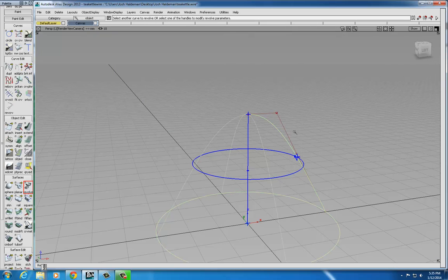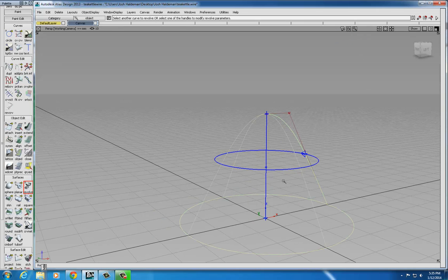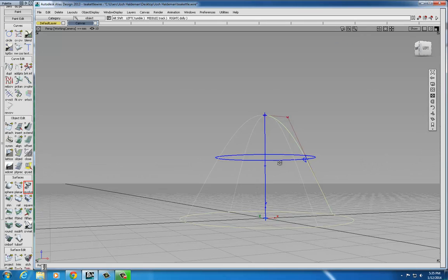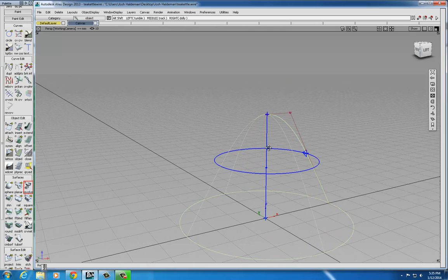One thing to know in this file is when you first open the perspective window in here, your camera is locked. So if you try and move around your scene using Shift and Alternate, you won't be able to do anything. It won't be able to move. Don't panic. It's simply because you have the render camera selected. The way to select the working camera is to go up to the top where you see this little icon here that looks like a camera inside of a box. And instead of having the render view camera selected, choose the working camera. The view looks slightly different, but you'll now be able to move around your object.